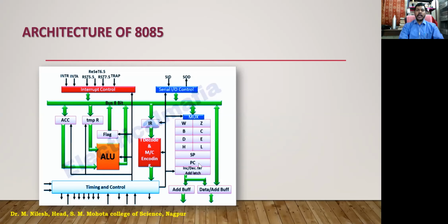Program counter. Now we have to feed the program in some memory location. These memory locations are recommended by different kits for different purposes. So when we say we are loading the program from 6000, 6000 is the first memory location, and then we go on storing the instructions in order.